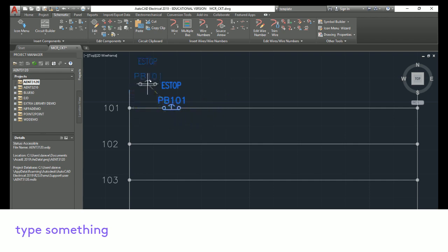So you can see this is really handy if I'm trying to get it to line up precisely to a line and for some reason it's not. So I can move a component around. Moving it around with the snap mode, it kind of bounces around. If I turn the snap mode off, it moves around smooth. And now I can just place that component wherever I want.